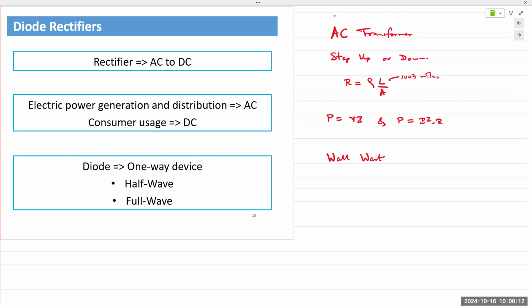Okay, they were heavy because they each contained a transformer. The transformer would step down the AC voltage from 110 or 120 volts down to a usable voltage of 10-15 volts. And that 10-15 volts AC would be fed into a diode. The diode would convert it, or rectify it, into DC, and that DC would then plug into your device.